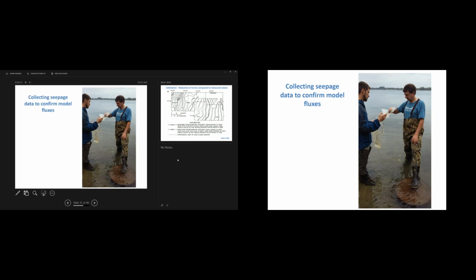So I'm standing on a 55-gallon drum that's cut off and pounded into the stream bed, and attached an IV bag to that, with a set amount of water in it. We filled it up with 500 milliliters. Put it under the water, connected to the drum that's otherwise sealed.